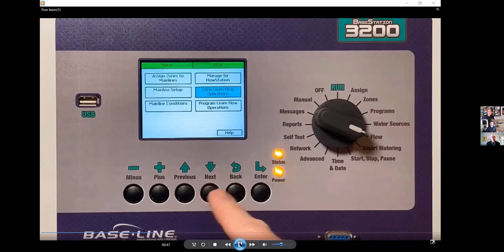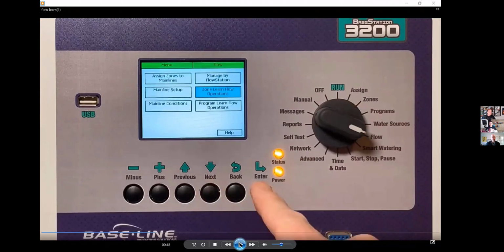And I'll point out, if you want to pause that for a second, Dan, when you're utilizing a baseline sensor, we pre-program the device with the K value. And so that's automatically loaded into the controller when utilizing a baseline sensing device. If you're using a third-party sensing device, such as a data industrial sensor, then you will want to make sure you bring with you or use your phone to look it up on their website to find their K value and enter that in. Right.